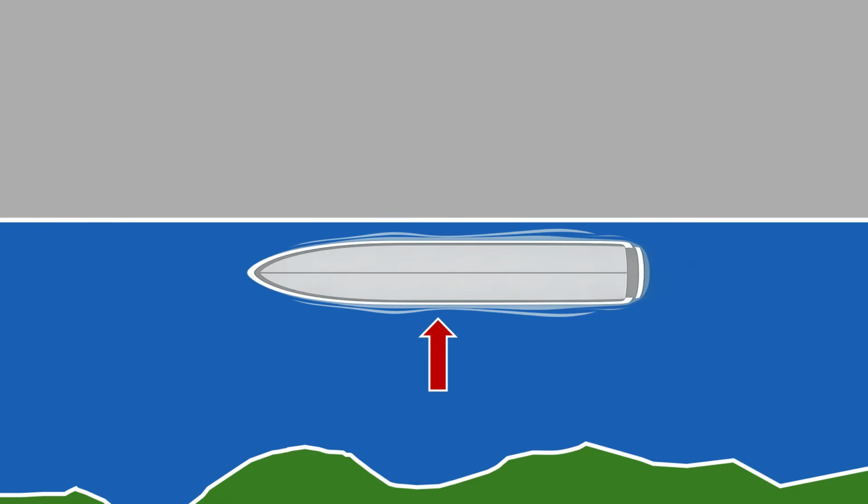In river ports, the situation is often different. There, the force of the current may control the design, especially when strong river flows act on large vessels for extended periods of time. In exposed locations, such as offshore berths or ports open to the sea, wind, current, and waves may all act simultaneously, and berth operations are often limited to specific weather conditions.